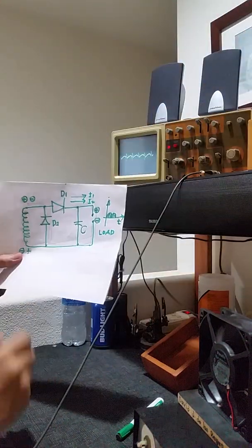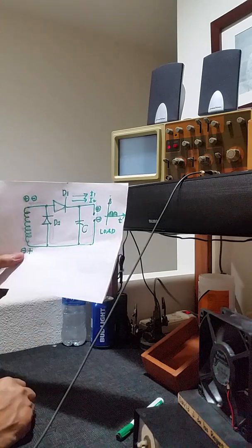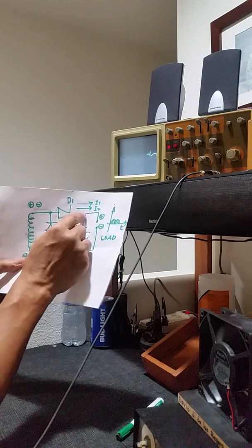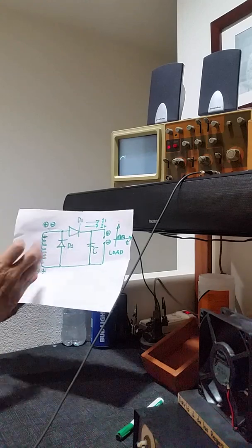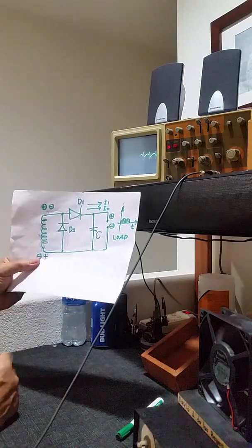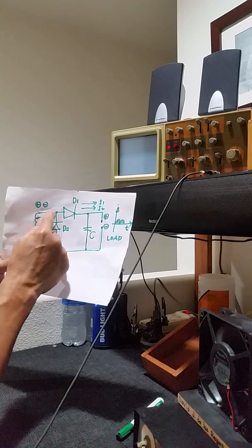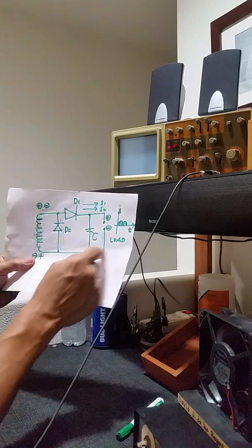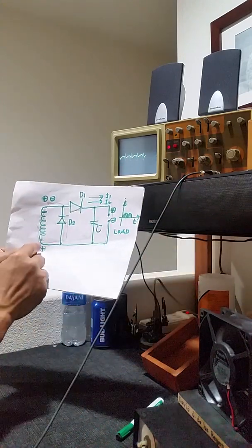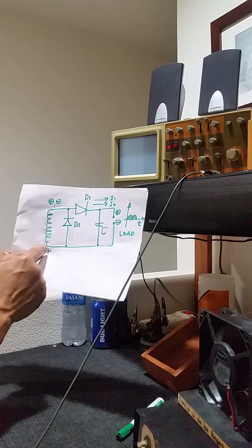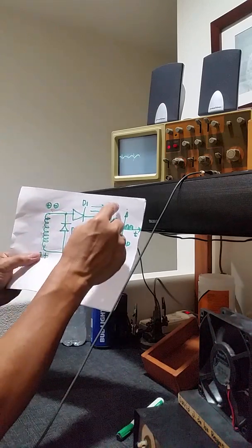But for a direct current, it passes through the load in only one direction. If it's coming from here, it always comes from here. It passes through the load, then comes back to the return circuit. So for alternation number 1, it will pass through diode 1, through the load, then come back to this terminal here. For alternation number 2, it will go up, coming from here, to diode 2, to diode 1, and pass through the load again.